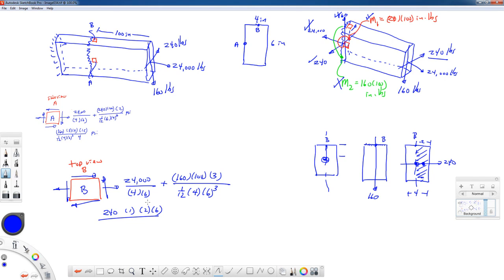If this 240-pound force causes a bending moment, that would be bending about the easy to bend direction. So another way to think of that is that it thinks that this edge perpendicular to the force is the base dimension. So the I would be 1/12 the base times the height cubed. And the thickness of the cross-section is the last term that we need. The thickness of the cross-section is the same, it's parallel to the base dimension. In this case, it's going to be 6 inches.